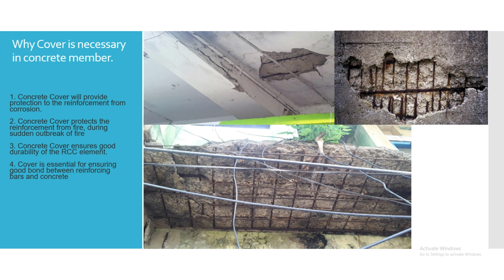On site we follow clear cover, not the effective cover. So the first reason why concrete cover is provided is that concrete cover protects the reinforcement from corrosion.